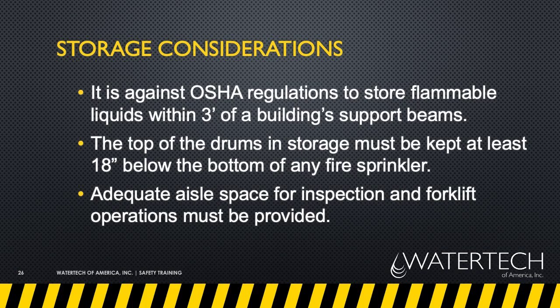OSHA states that flammables cannot be stored within 3 feet of a building's support beams. The top of the drums and storage must be kept at least 18 inches below a fire sprinkler. This is important when the products are being warehoused and pallets are stacked up to the ceiling. Lastly, adequate aisle space for inspection and to safely operate a forklift must be provided.